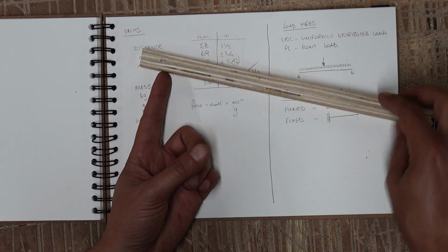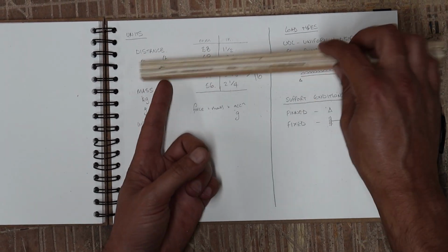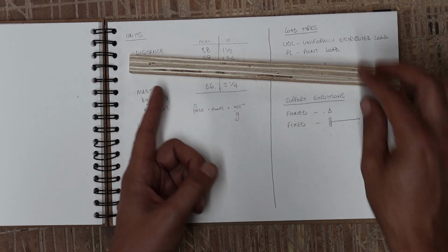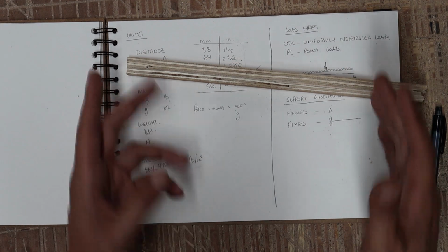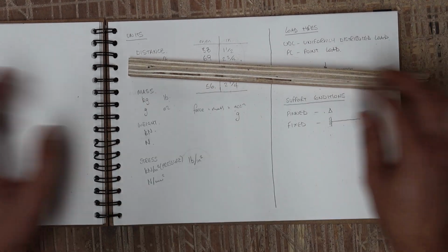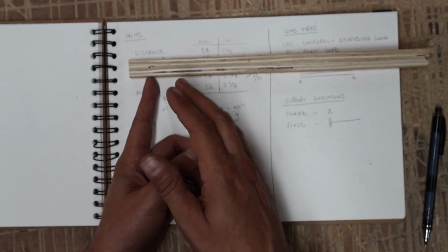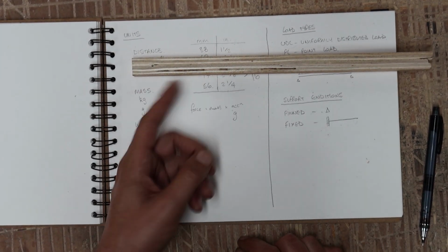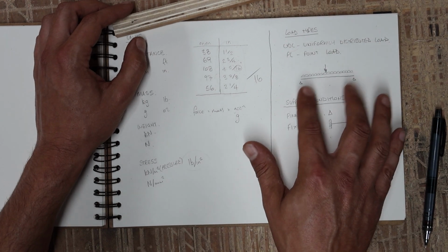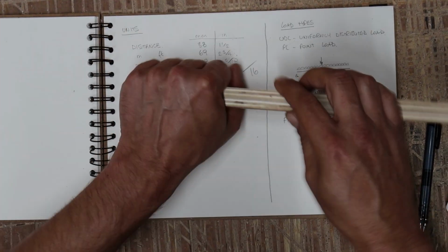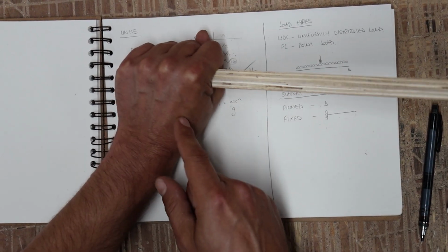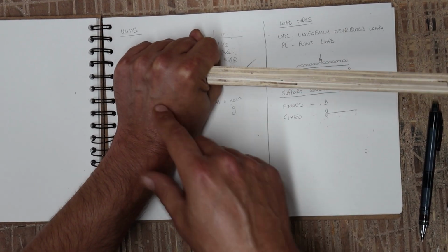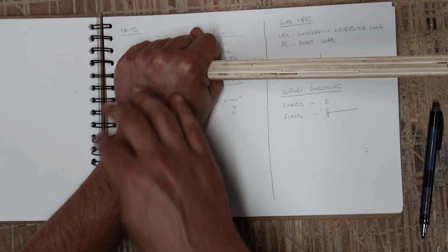There's no equilibrium being developed between the forces being applied to the member, and as a result, it's moving and it's a mechanism. On a very basic level, that's our first job as structural engineers, before we do anything else: we look for collapse mechanisms and how to prevent them. Now, as I said, with most beams we just do pin supports, because fixed supports are really onerous on the structure. That's quite a lot of load to go back into the structure, so we try to avoid this situation when we can.